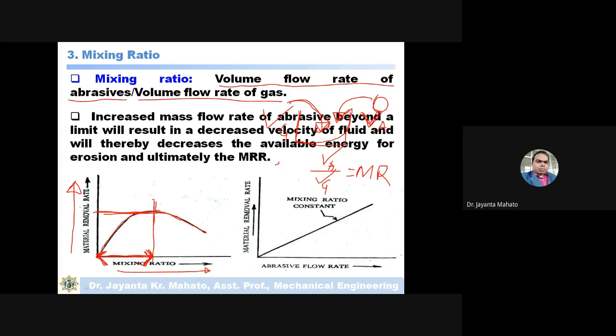And if you increase the flow rate of abrasive particles, the material removal rate increases linearly. There is no maximum limit and then falling down. So if you increase the abrasive flow rate, the material removal rate will increase linearly.